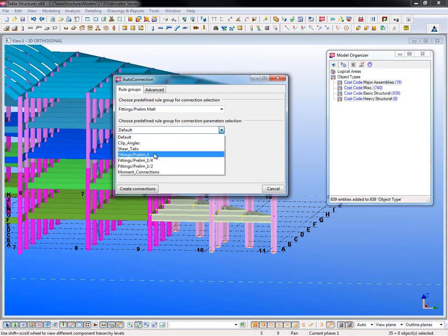If you put on fittings, you can set this back to where, if you had a beam coming into a column flange, the way that we have it modeled is point to point. So from the center of the column out to the end of the flange is basically just going to be extra. This is going to be junk material, right? It's going to be thrown away. So you could apply the fittings to have it cut back to all of the different faces.